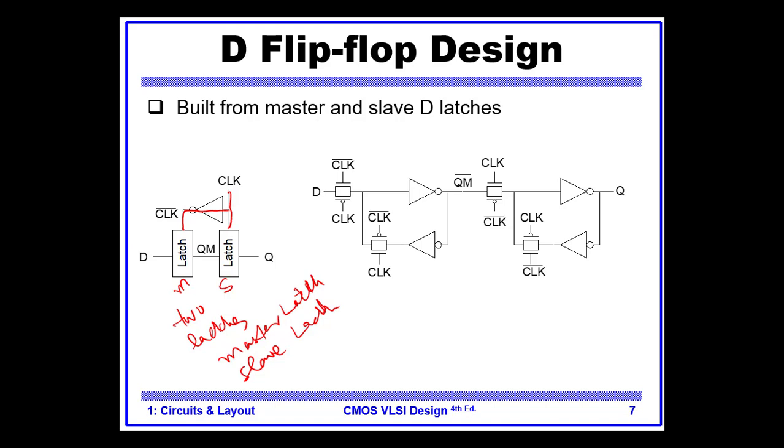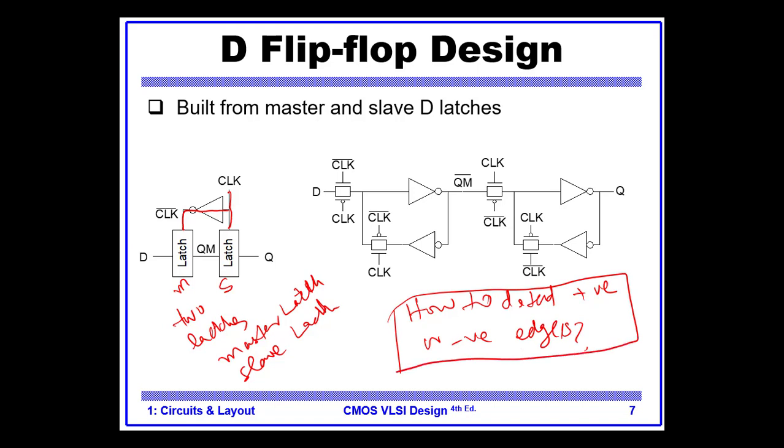Okay, so this is how the master-slave works, and this combination is actually very interesting, because in a digital circuit you can ask this question: how to detect the positive or negative edges? I mean, we are just using latches, and as I told you before, a latch has nothing inside which can detect the edges.